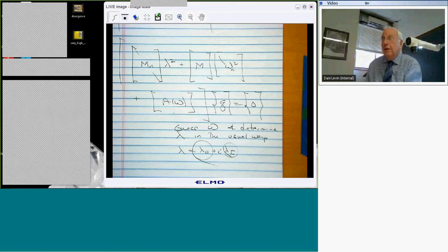What are the chances of that happening? Slim and none, as we say. Not likely. On the other hand, if you've been doing this for a few years, you can say, last time we built an airplane like that, and now I know what the natural frequencies are. I bet the two modes I think are going to couple are the mode at 5 hertz and 15 hertz. I bet the flutter frequency is going to be 12. And by the way, this plane is a little more flexible than the last one, which fluttered at 700 feet per second. So I think this one will do 600. Okay, it's not like you are totally clueless as to what a good guess would be.